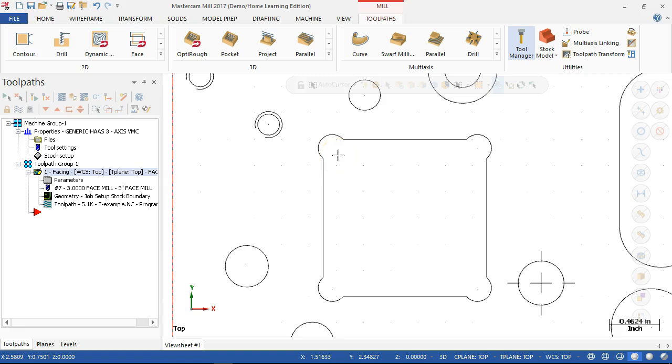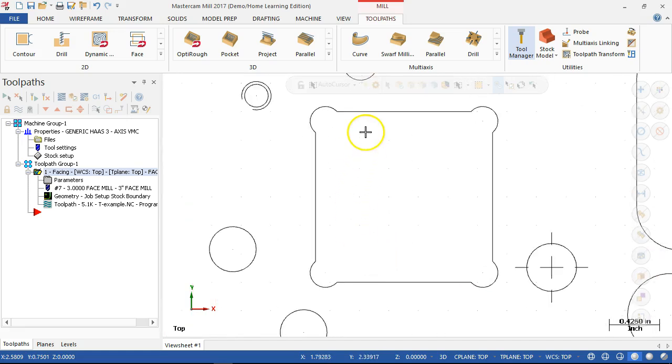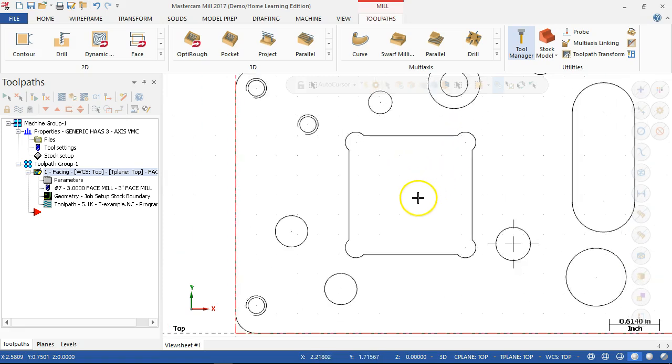All right, so in this case, this is basically a line over the corner, and we have about 10 to 20 thousandths of clearance from that square corner contacting that arc. All right, so square to square. So the advantage here is that I'm going to be able to pretty much take my 1/4 inch end mill and run it pretty tight into that corner, at least on the pocket, and the finish will be able to get in, clean it out, and get it clear.